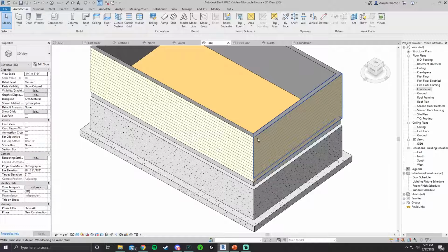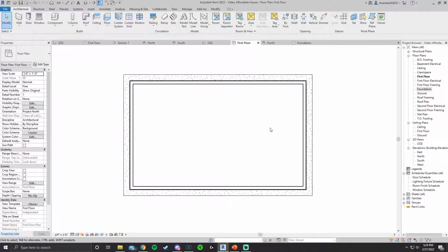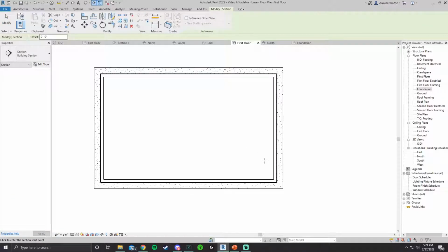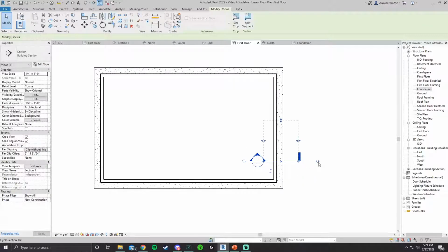From here, we're gonna be working in our section view. So a lot of steps to this, but just bear with me. We'll get through it. So first, I'm gonna create a section view. Up here on our icon bar at the top, if I go to section view right now, I'm just gonna go ahead and make this. And again, you can always flip this. So I want that black bar on the inside, and then there we go. That's good.